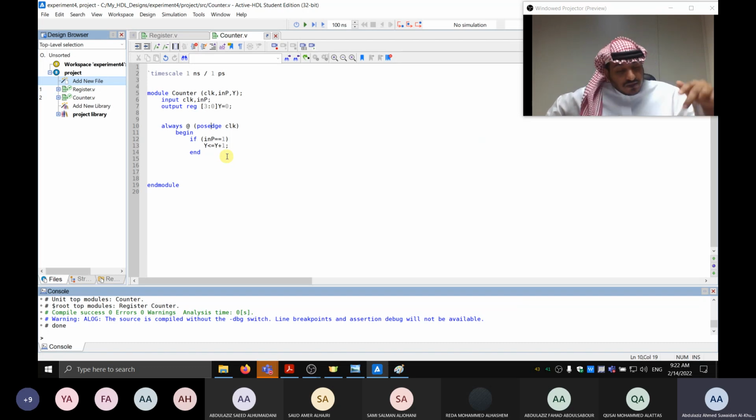I want, whatever the type of pressing, if I press the button, to count only once, not many times. And I don't want to miss it, like a case where you press a button and nothing happens, as in some equipment. If I press the button, it's guaranteed that it will count only one. So I have to fix it. I cannot fix it in this module. I have to fix it in some other module.